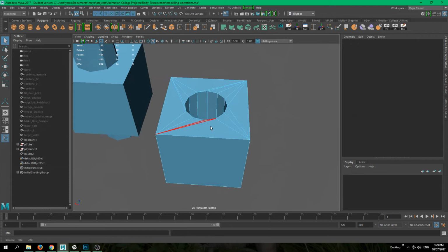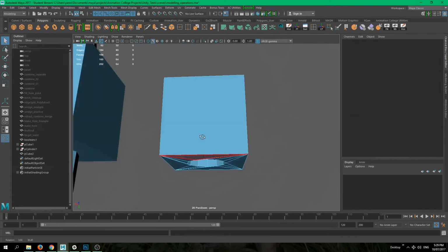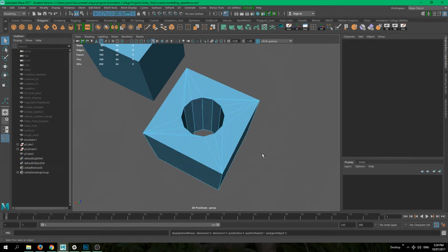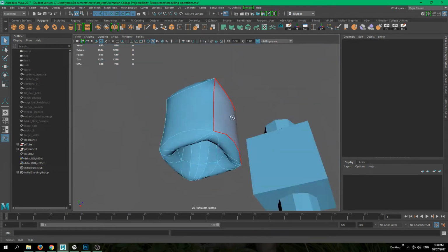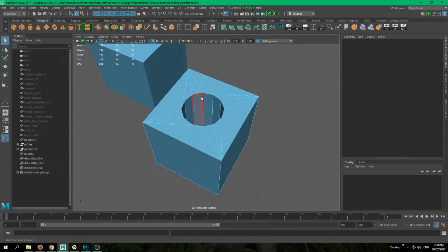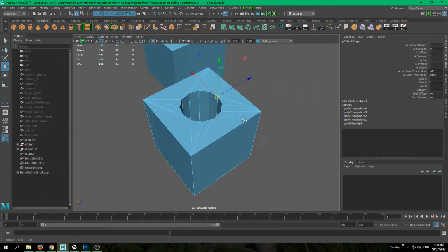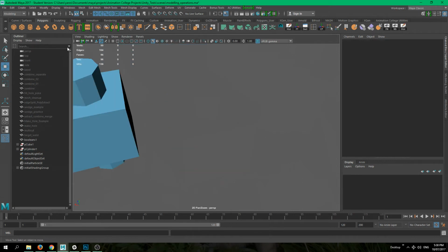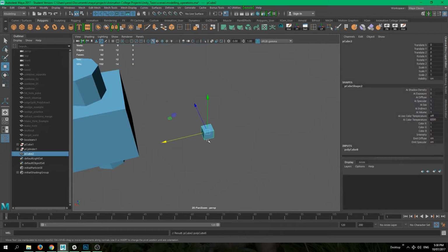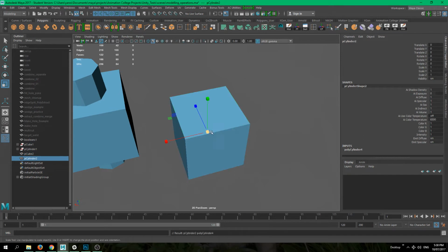So it's not ideal, but at least you don't have that problem with the n-gons anymore, and everything is sort of connected. Kinda. I'm just looking in the smooth mode, so you can see that it's not a very nice shape, but it works. And you can always check if everything is properly connected by just dragging vertices around. And the last thing we will take a look at will be our intersection operation. So we have a cube here, another cylinder as well.